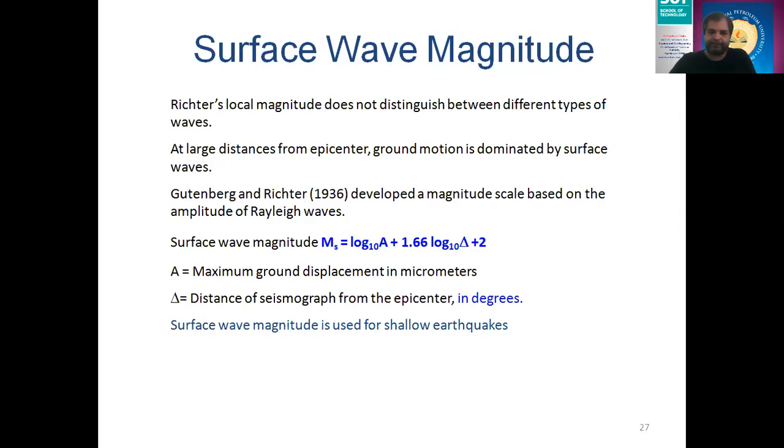Suppose the earthquake happens somewhere in Bhuj and you have the seismograph station somewhere probably in Delhi, which is almost 1050 kilometers away from the epicenter. In such a situation, which particular seismograph will record this value, and which particular magnitude scale is being used? In such conditions, probably the surface wave magnitude will give us the solution.